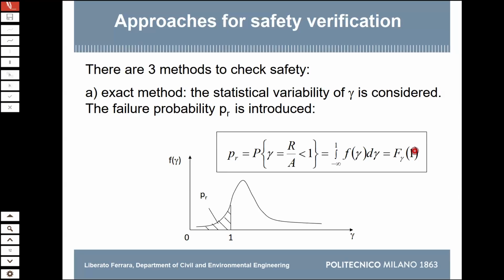And then there is also the possibility of populating this database with a Monte Carlo analysis. You have your structural model in whatever software, and you plug in some routines which tell you, for example, that the dimensions of your beam change with some kind of probability distribution, that the strength of your material changes with some kind of log-normal distribution.